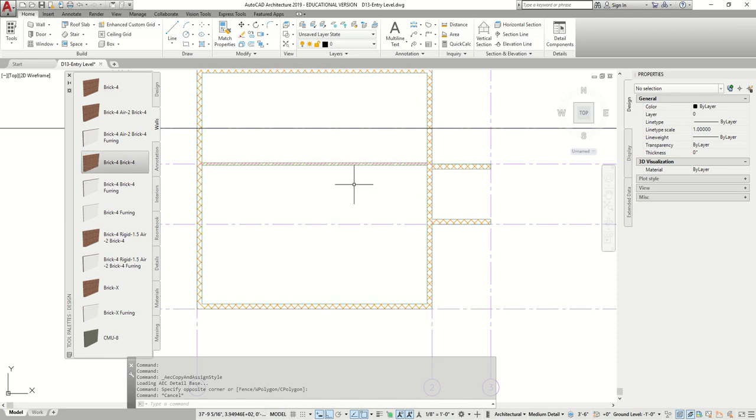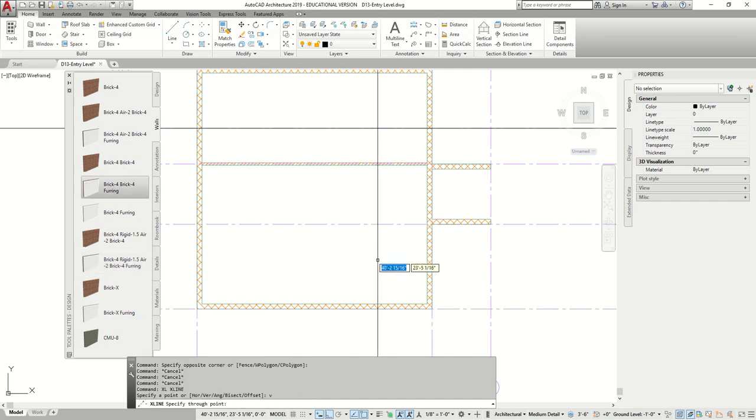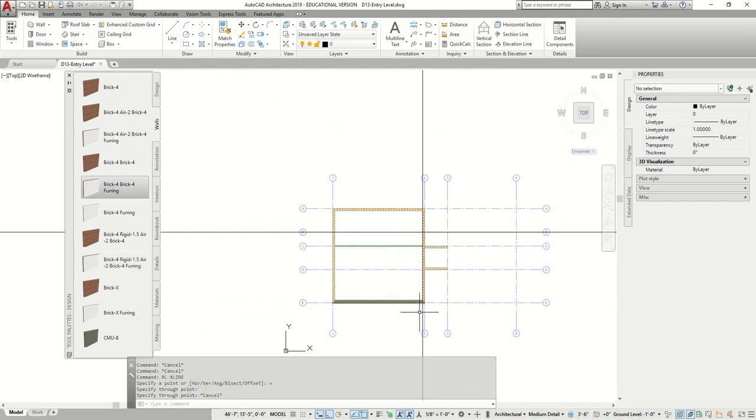So after closing the wall type, we're going to go make another one. There are 2 techniques for editing vertical internal walls from an existing wall. One internal is specified by construction line, and the other one is by the object tracking. So remember, we draw and we track it across. So what we can do is this, X line, vertical.